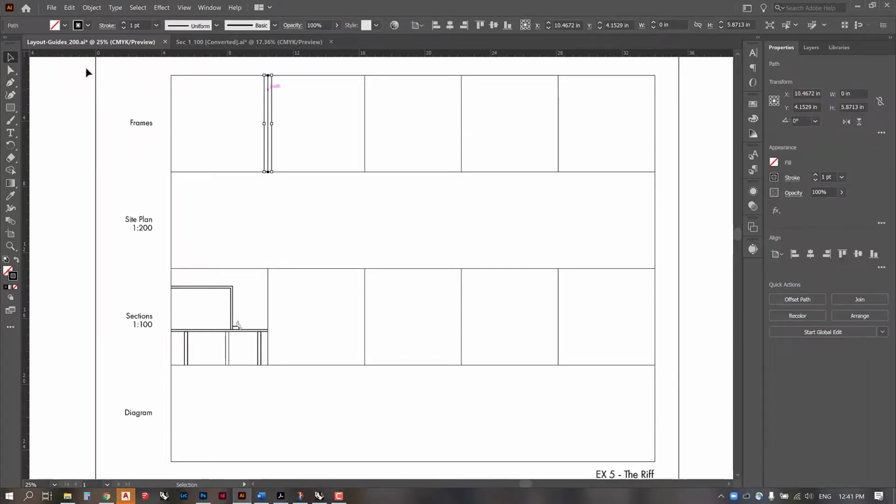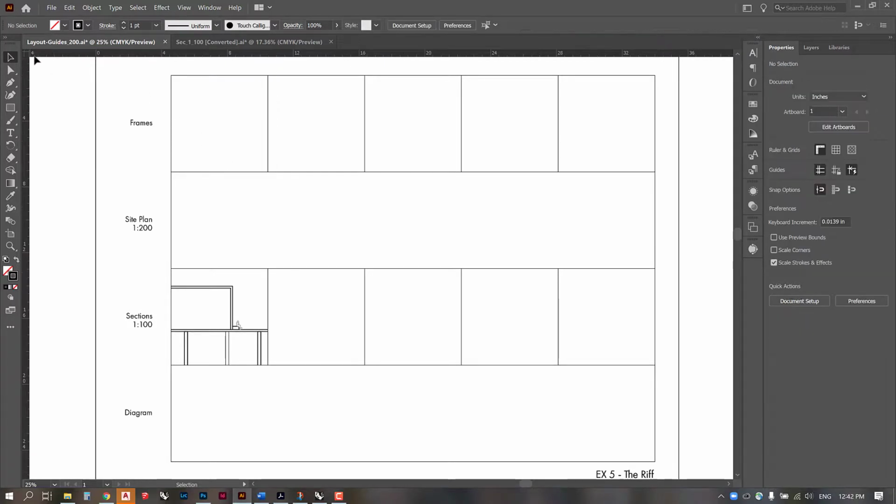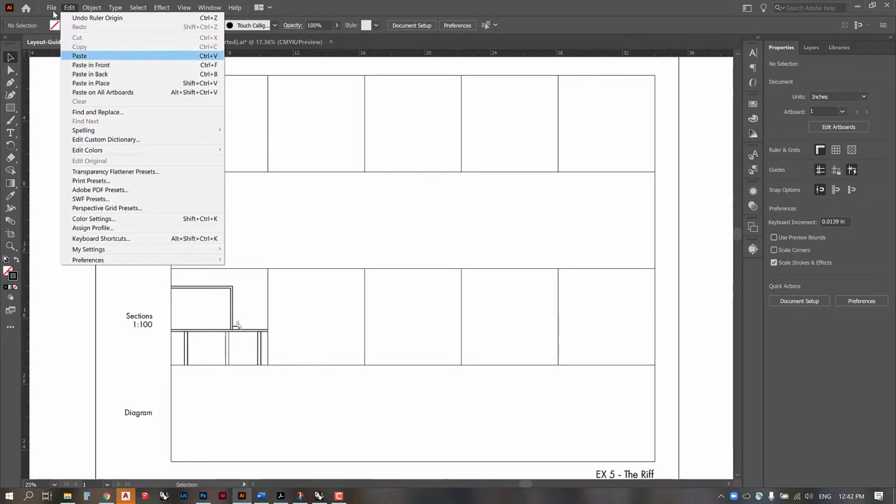Now, if we drag this to the corner of our object, you can see the rulers adjust to measure that object. And if I look over to the side here, I think it's 5 point something inches. So if I look at my properties, that corresponds to the height. That makes sense because this is a vertical object. So just be aware that if you want to know how big of visuals you need to make, 5 to 6 inches in this case is probably going to cover it.